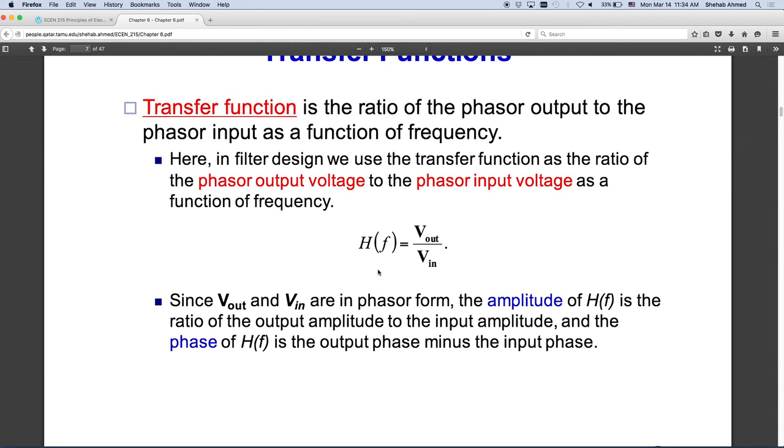So, for example, in the car example as well, complex quantity means it has a magnitude and an angle, right? So in the car example, take two cars with different transfer functions. Let's say the magnitude was the same, but the angle was different, and two people push the pedal on the car exactly the same amount. What will happen in this case? The cars will definitely go to the same speed because the magnitude of the transfer function is the same. But because of the phase angle, one will be delayed with respect to the other. That's physically the interpretation of that.